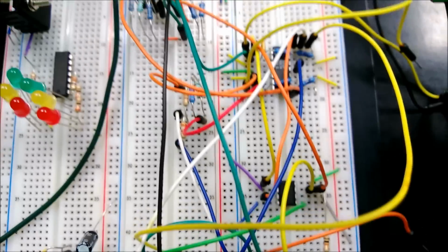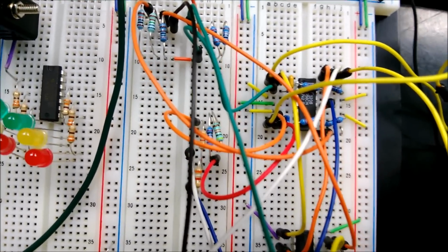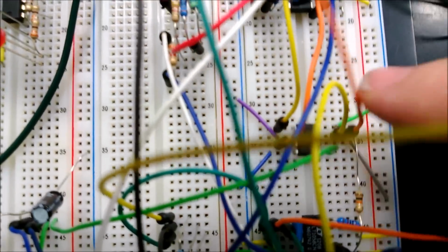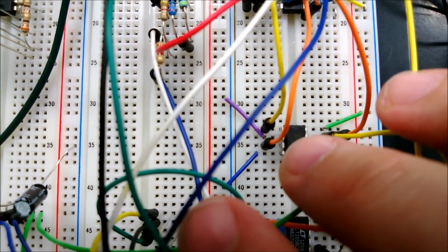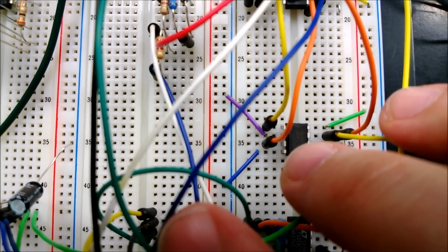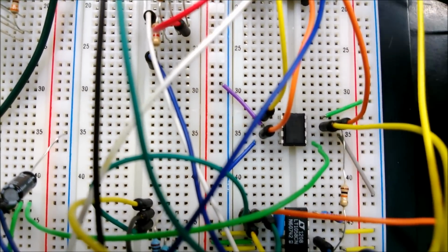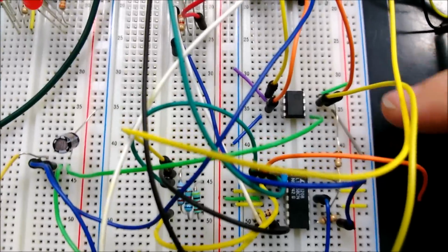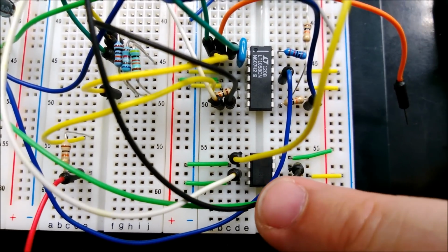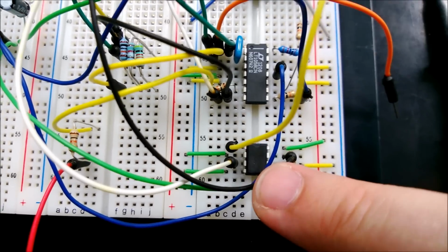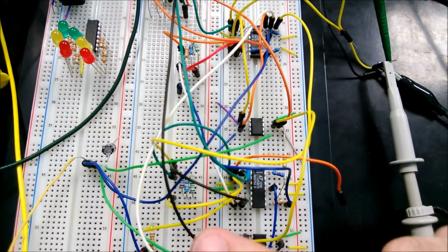One other thing is that, other than the LT1058s, we're making use of some AD633s. These are multipliers, and we're using them to take two inputs like a negative x and the x, and then we have the output over here of minus x squared. We then take that minus x squared and use it with another multiplier with another minus x, so that we end up with a positive x cubed. All of those are what we end up with to have each one of these inputs over here.